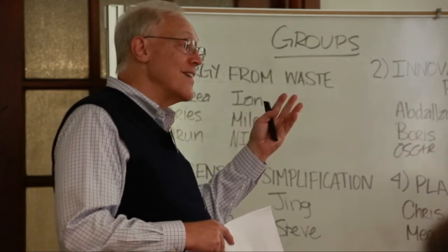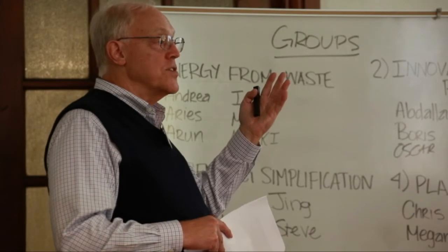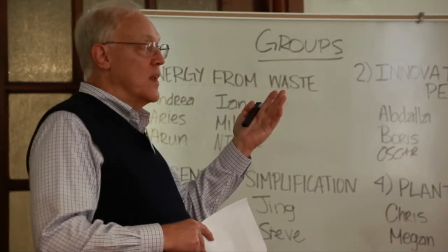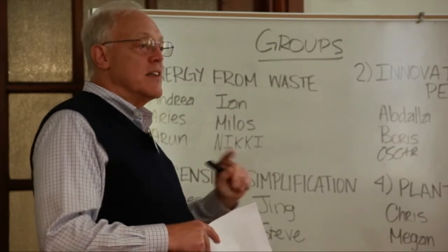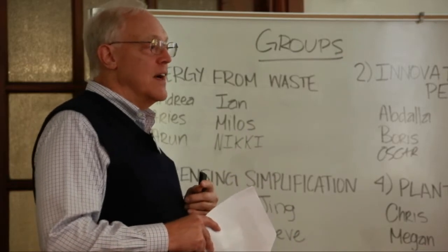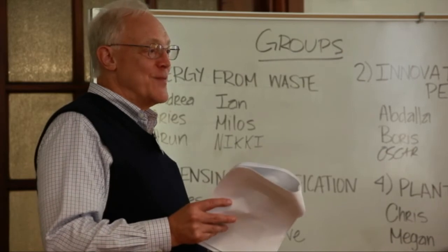Core is heating up. Okay? We were within 10 minutes of damaging an intact core, just like TMI-2. Okay? Management made a decision not to go there. Why? Well, in feed and bleed, the bleed portion is out through a safety valve, and the safety valve dumps on the floor. We're going to get the plant messy.